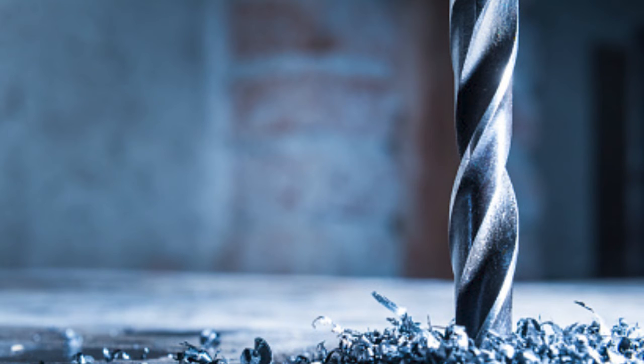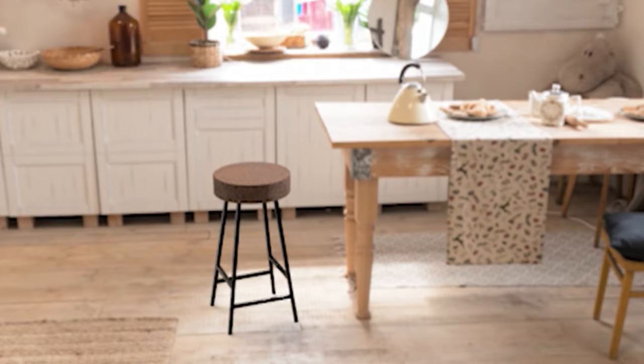Then lastly, the holes should be drilled into the base plate, and then the 2 pieces, legs and seat, will be screwed together with 8x35 screws. The final product is then completed by placing the end caps on the end of the legs to avoid scratching or loud noises from the stool.